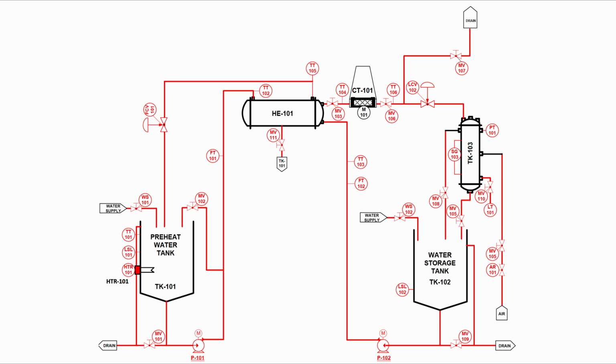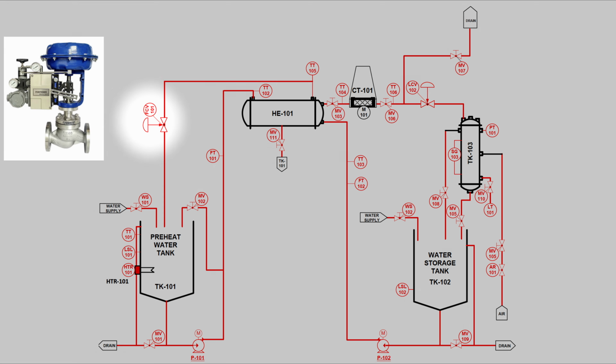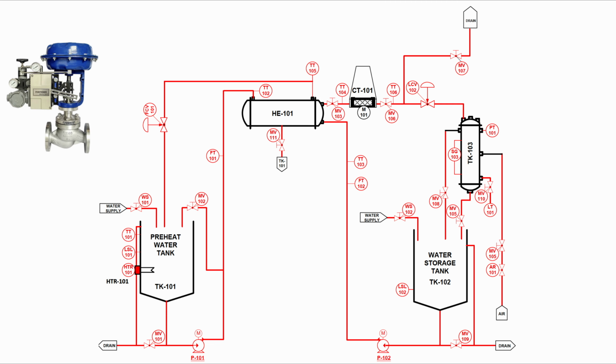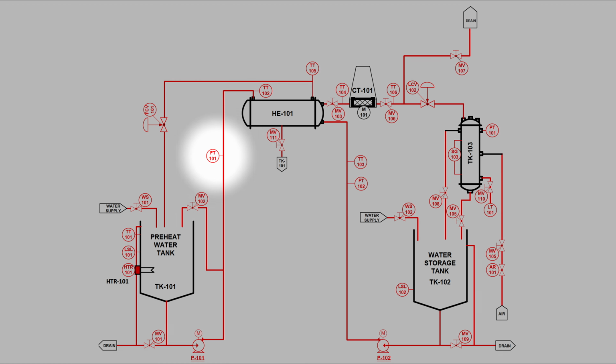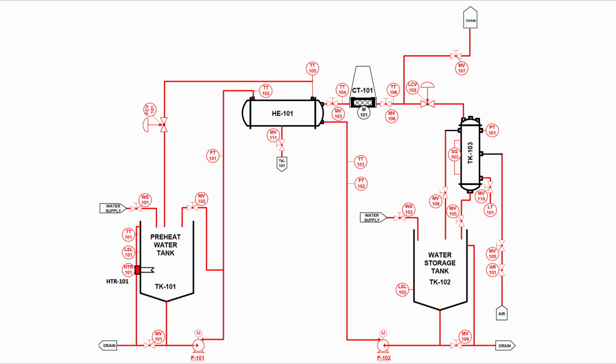In terms of the actuators, the regulated control valves CV101 and CV102 are opened at 100%. This is to allow a maximum flow rate, measured at FT101 and FT102. The experiment will be done in 1800 seconds. This is to allow the heat exchanger to achieve a steady state.